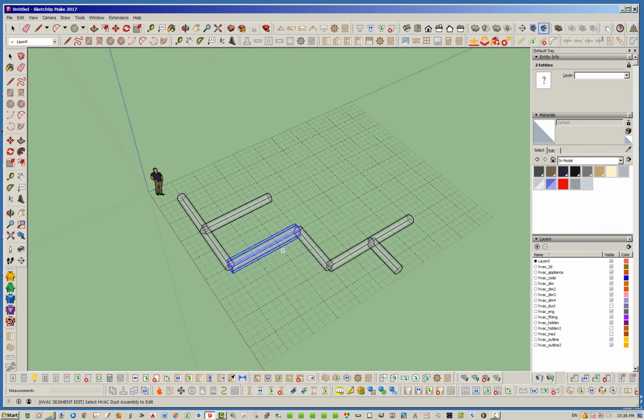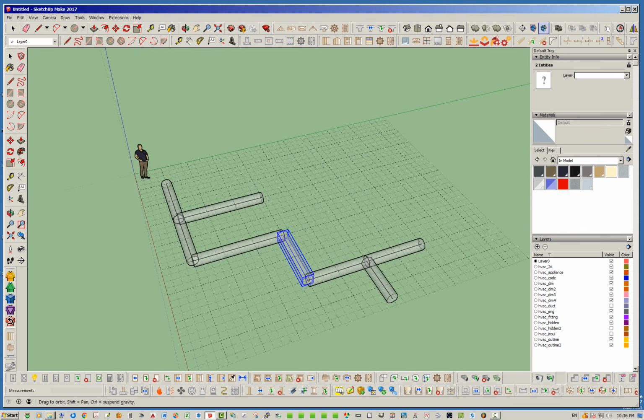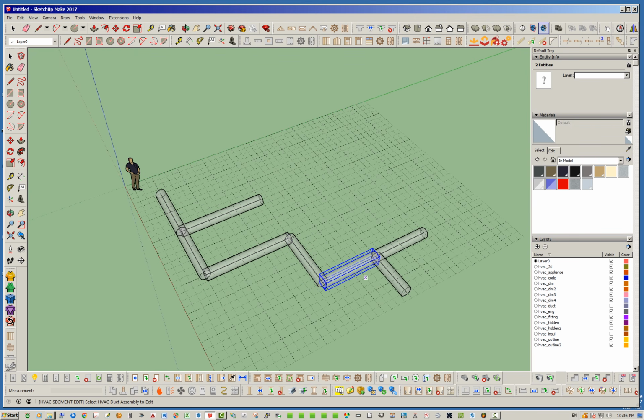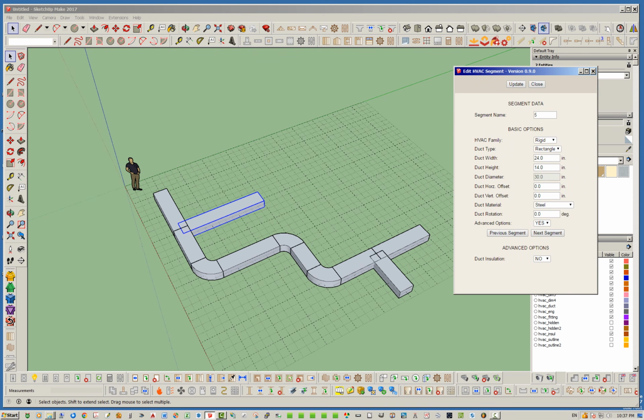When you click that, you'll notice you get this transparent wireframe happening, and there's a good reason why I do this. I'm hiding the actual ducts and presenting a bunch of primitives that you can mouse over and select. Sometimes when you get ducts right next to each other, they may not actually be drawn, but the primitive will still exist. Anyways, we'll get into that later.